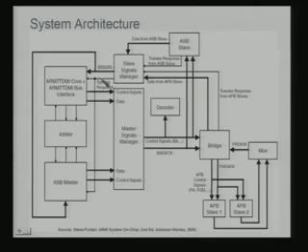This is a transfer response: what is the response to the transfer transaction which is currently being executed? And this is your data which flows from the slave back to the master. And this is where the arbiter is. Once the request comes in, the arbiter resolves and gives a grant to the core. Only once it gets a grant is the transaction initiated.